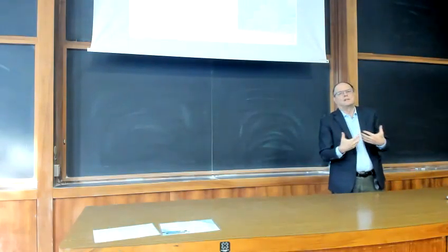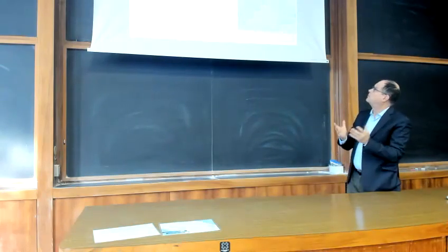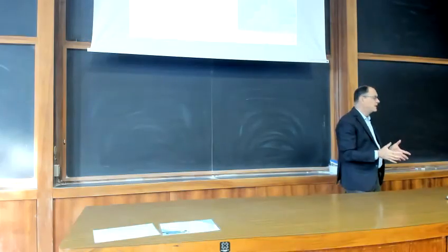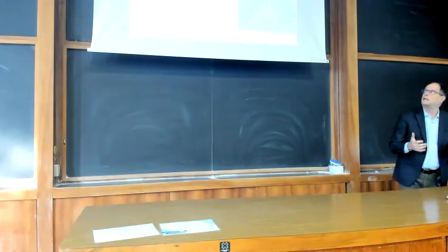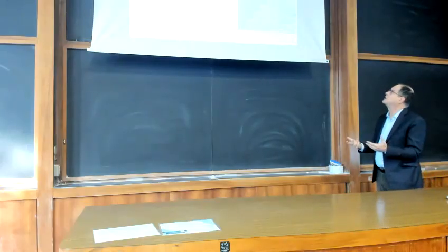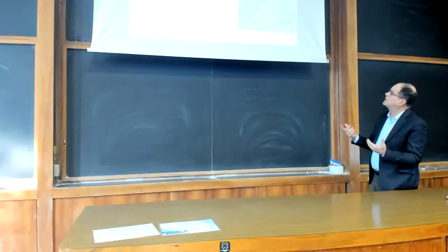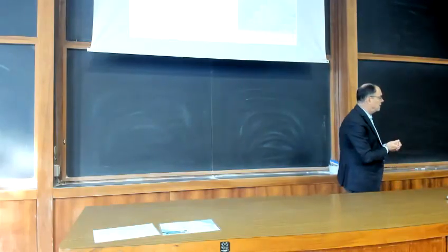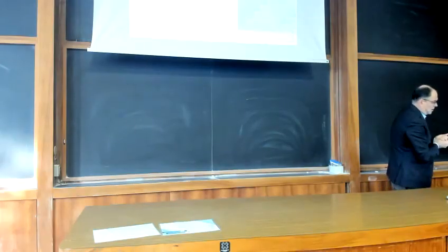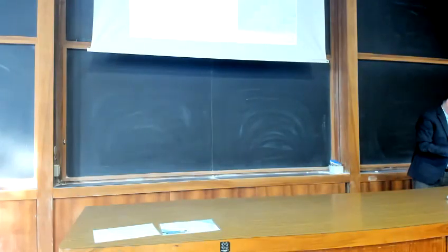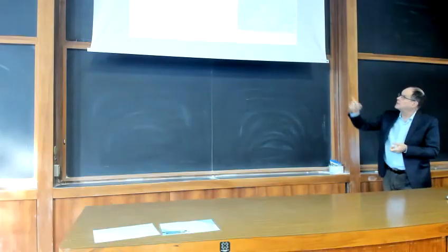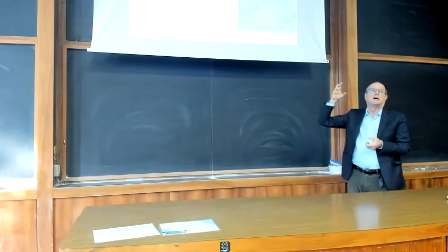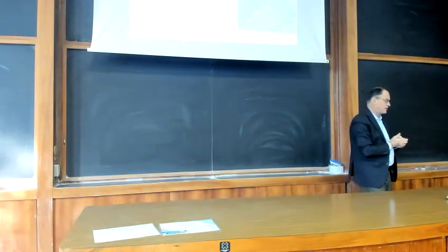Of course, they are all part of the same design, but first we have to define actions on the structure. Once you have defined all the actions, then you can design it as a structural element. And of course, in this case, the geotechnical part, which is the most critical part, is to define the force P, which is the force that the soil behind the structure exerts on the structure itself.